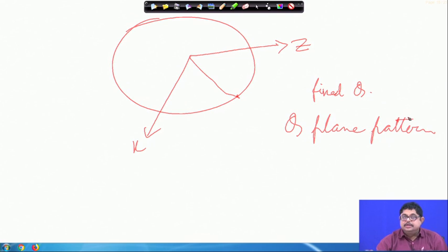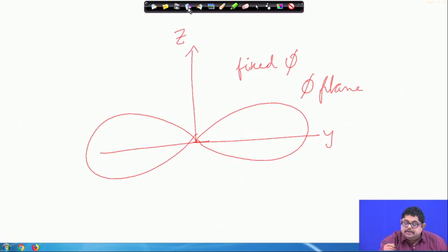So, power patterns of antennas are like this. It shows that in the azimuthal plane a current element does not have any variation, it behaves like an omnidirectional antenna, but in the phi plane it behaves like a dumbbell. So, in this direction it is giving more power than another direction, and at the current element line or axis it is having no radiation.